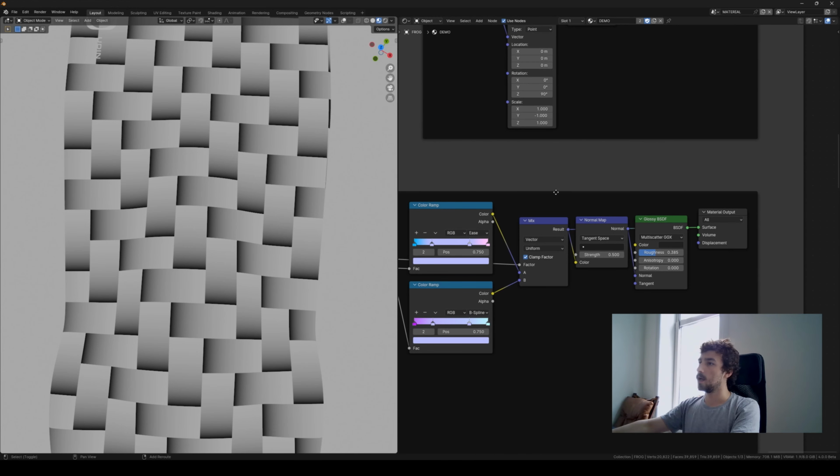And as we said before, now we have a lot of control over this. I can actually show you here if we would go with a different value here. Then we can create a different way to repeat the fiber. So if we have 0.1, then we have this just 1 by 1 type of carbon fiber, and we were at 0.05. And that's classic 2 by 2 carbon fiber.